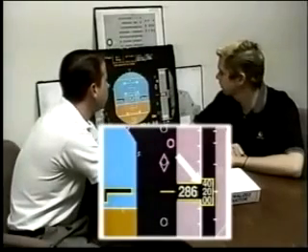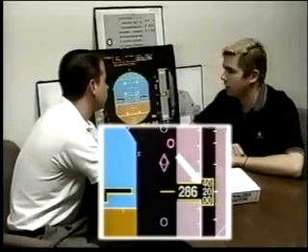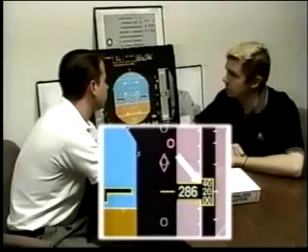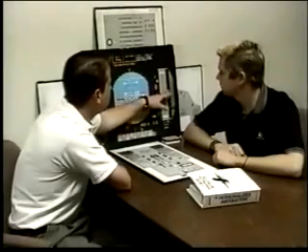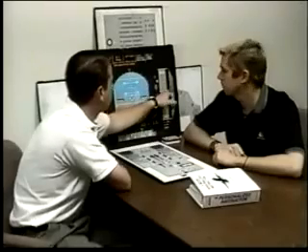Will you get an altitude alerting? Only if you're hand flying. If the autopilot's on, you don't get an alert. Okay. You're at the selected altitude and you deviate more than what, the box will turn amber. It's 250 feet. Will you get the altitude alerting then? Yeah, anytime you deviate by more than 250 feet, regardless of the autopilot, you'll get an alert.